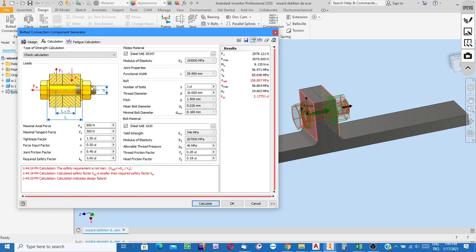Replace the bolt with one manufactured by another company, a more reliable company with a better manufacturing quality assurance system. So for such a bolt, for instance, not 3 but 2 is enough as the factor of safety, 2 times on the safety side. Then calculate it again.